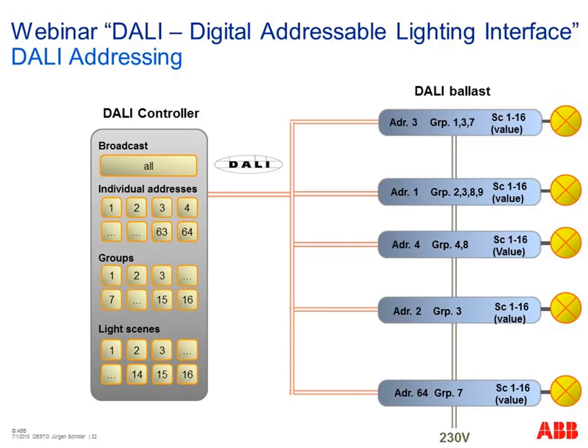A small practical example of which typical functions we have in a DALI system. What you see here, a bit abstract, is on the left a DALI controller, any operating element, so let's say the master, to operate any slaves, and the slaves are DALI electronic ballasts operating any type of light fixtures behind. So for each type of light we have a dedicated DALI ballast necessary. But Jürgen will show you later on some examples of products. All these DALI ballasts are connected in parallel via a 2-wire cable to each other, and also to the master, of course. And as we have power necessary for the lights itself, we need also 230 volt.